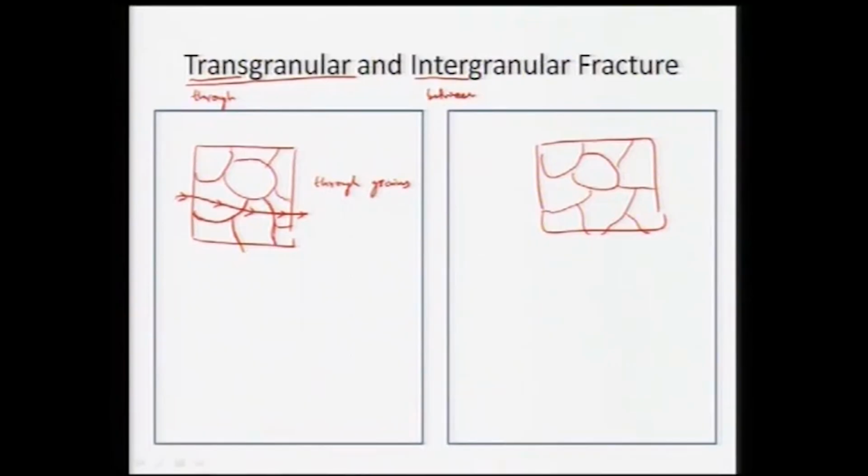Apparently, if we have a nanocrystalline material, meaning a material with a very fine grain size, then the crack has to encounter grain boundaries more number of times, and in the process we will see a very enhanced strength of the material.